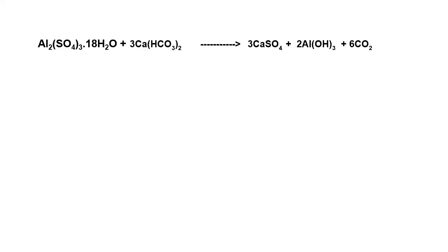Okay, so the dosage depends on what? Dosage depends on the turbidity of the water, the concentration of suspended particles. Now we will identify this in the laboratory. There is one column test. In that test we will do this and identify how much dosage is required. Understood? Okay. Now how to use this equation practically, I will explain later.